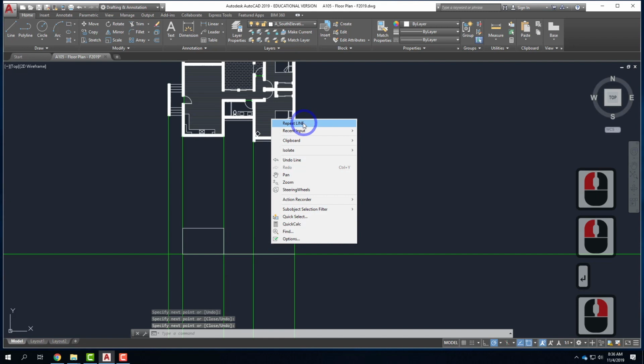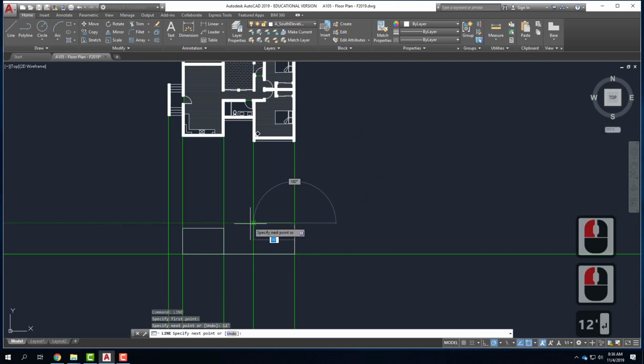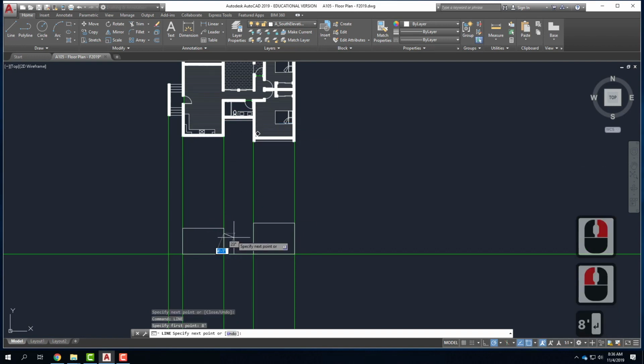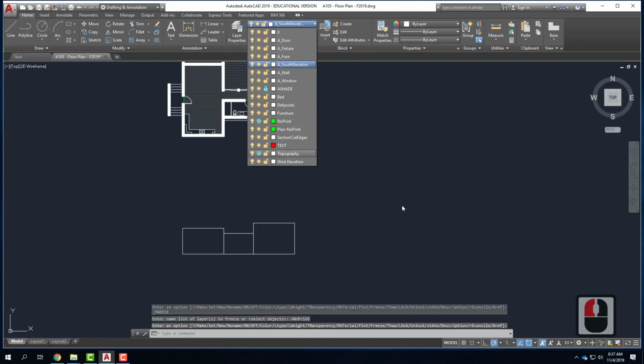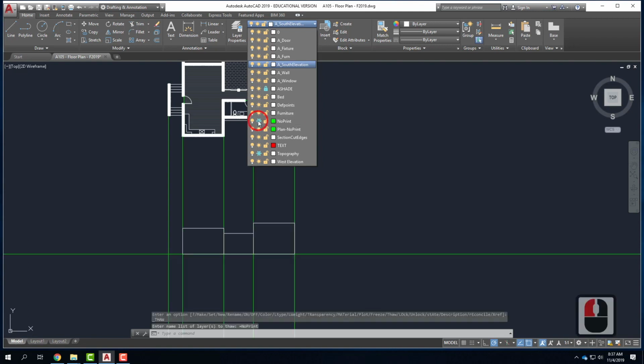And this side over here, I'm going to do it at 12 feet. And I'll come back down. And my little bridge section in here, I'll do it shorter. So we'll do that one more at 8 feet. So I'll come up 8 feet and go over like that. If I turn off my no print layer for a second, you can see that I'm essentially massing out boxes for what this building is going to look like. So I'm starting with kind of general massing, and then I'm going to continue to add detail from there.